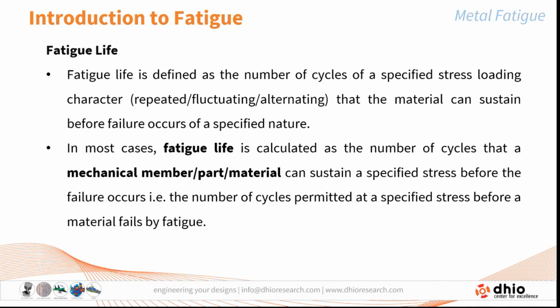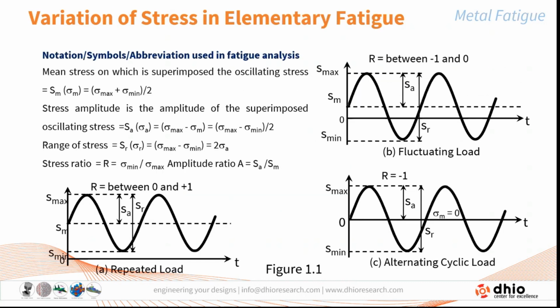Now, in most cases, the fatigue life is calculated as the number of cycles that a member or a part or a material can sustain at a specified stress before the failure occurs. That is the number of cycles permitted at a specified stress before the material fails by fatigue. That means you have a specific value of the stress, then calculate for how many cycles it is going to last before it fails. The number of cycles which it can sustain for a specified value of the stress is what is called the fatigue life of the member.